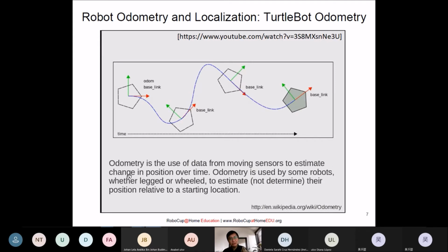So we use odometry with the model in mind, and you can also get the speed, because on your motors you can put encoders to calculate the speed of rotation. From there you can do all the conversion and get the distance traveled. So you use this concept to calculate how much the robot is supposed to move in the environment.